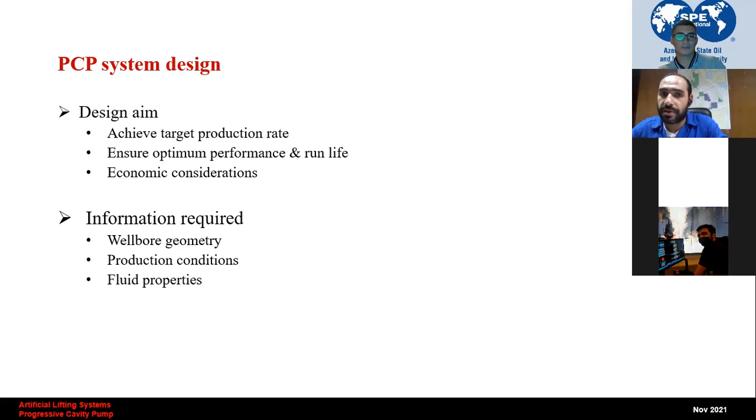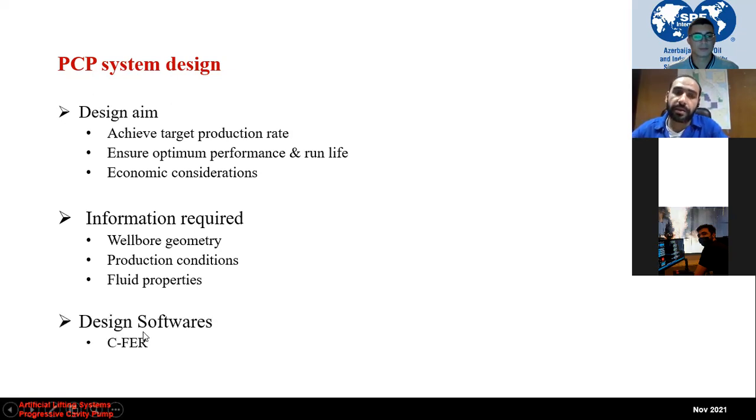Remember, the elastomer is just waiting to deal with the fluid. The elastomer designed for normal applications cannot withstand H2S or high aromatic content fluid. We need to know the water cut, the sand cut, viscosity, density, aromatic content, H2S, and carbon dioxide. So all these must be known. Design software is not so common for PCPs, and Separator is the most commonly used one.